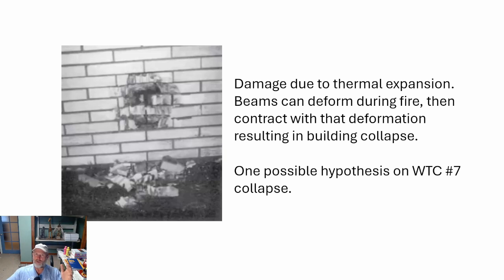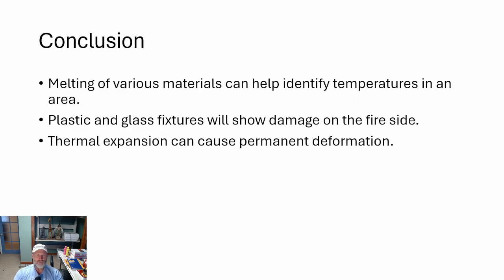So not only do you have thermal expansion, you have thermal retraction, but it maintained its strength as it went through that retraction process, having already been deformed, and thus the retracted size was probably much less than the thermal expanded size. In any event, it was very likely the floor beams pulled those girders off of their supports, resulting in the collapse. So it was a series of events that transpired there, but it's just kind of interesting to consider those things.